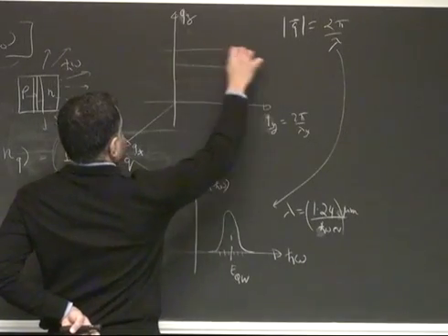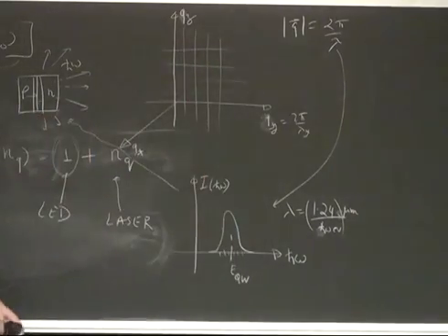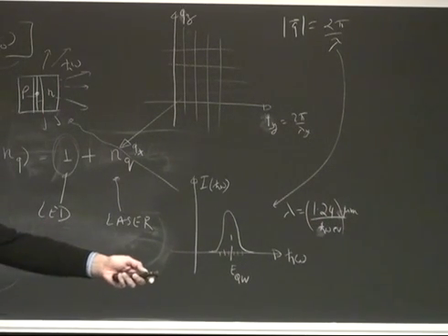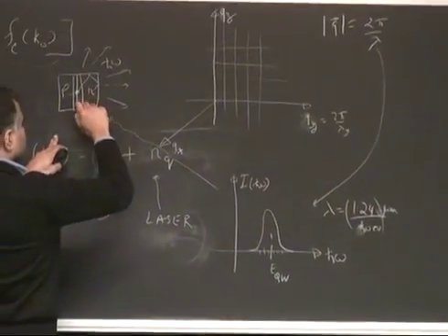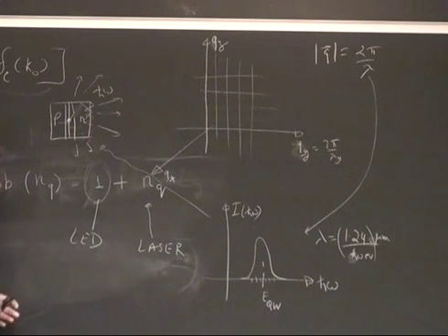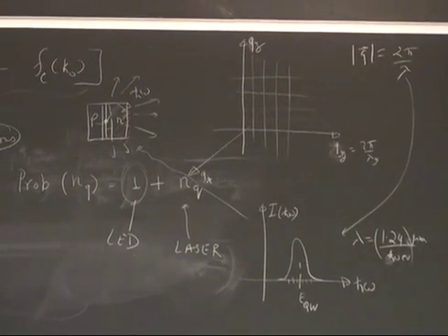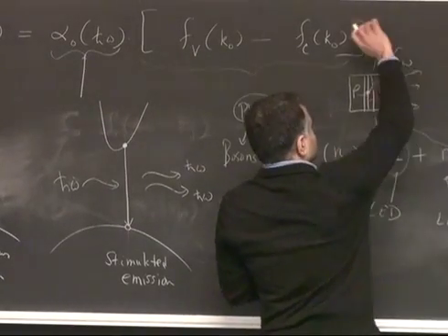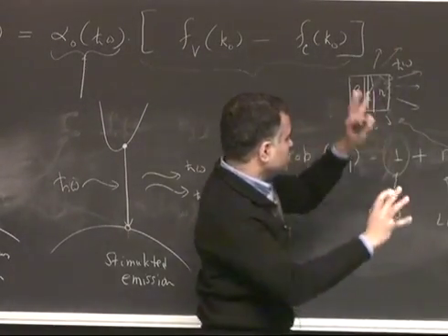So that's the magnitude, but the direction. What happens now is if the LED is sitting in vacuum, let's say, or in air, then the light can go out in any direction. Actually, let me put it this way: the direction in which the light is emitted, that's where all these thetas come in. These thetas tell you what direction they are going in. Generally, it will go out as a cone, but then it will try to get out and get reflected, so you have to do some stuff to get it out. What people typically do in industry is intentionally roughen the surface, so that there's always a path for it to get out, so you're not below the total internal reflection. Anyway, what I'm trying to get to is emitting into vacuum and into air.